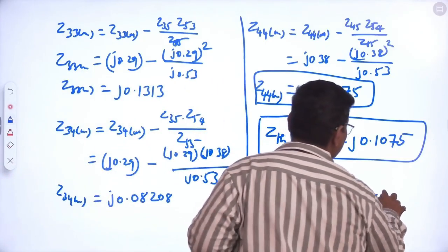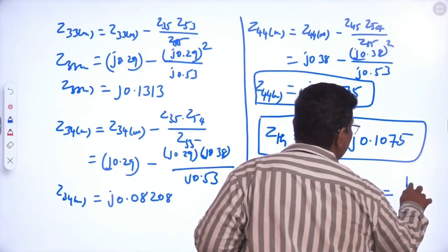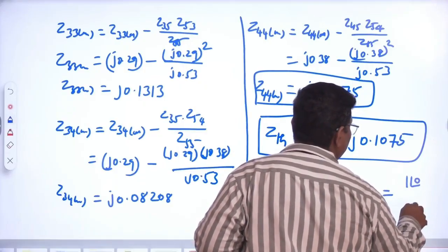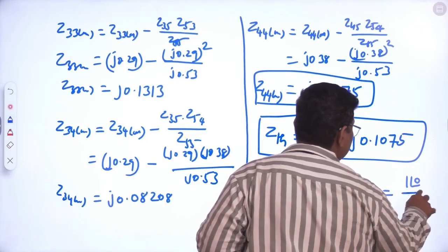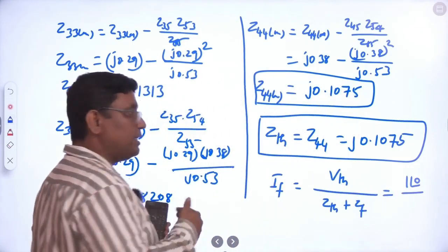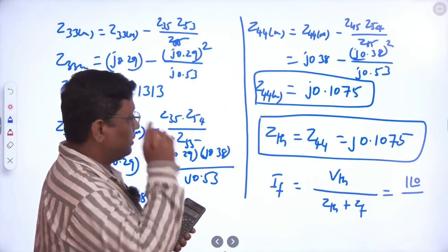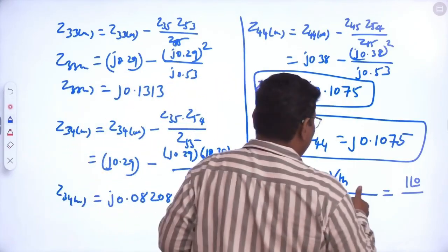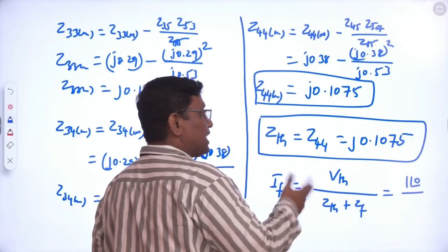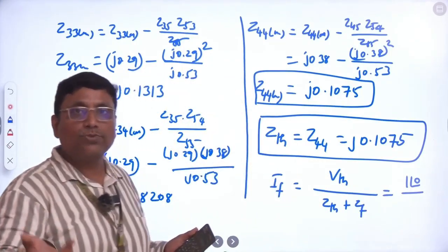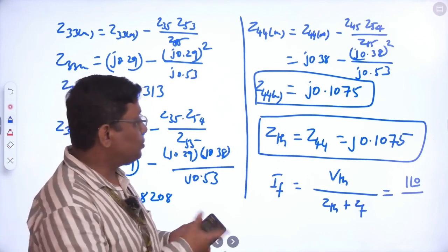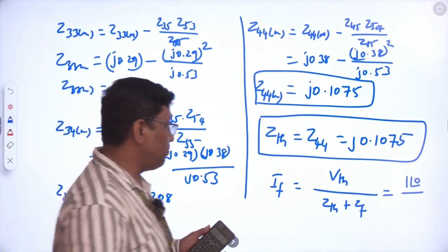So V Thevenin, the pre-fault voltage is default 1 angle 0 degree. Why? Because generator 1 and generator 2, in both the cases we are getting 20 kV value, right? So the pre-fault voltage is also the same. Actual voltage and base voltage value is also the same. That's why it's nothing but 1 angle 0 degree per unit.